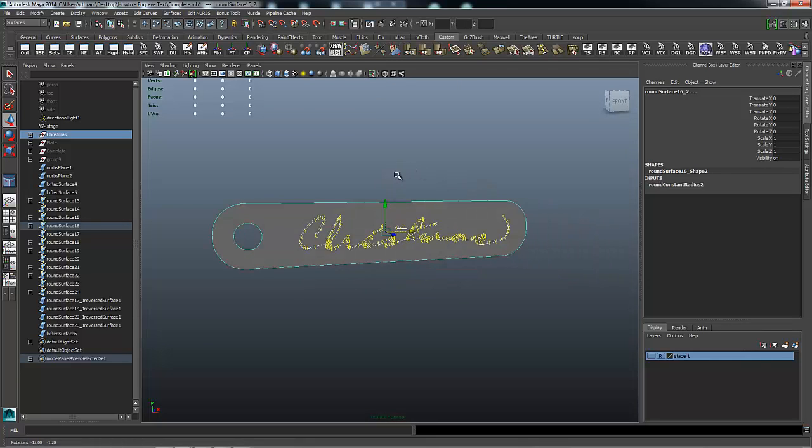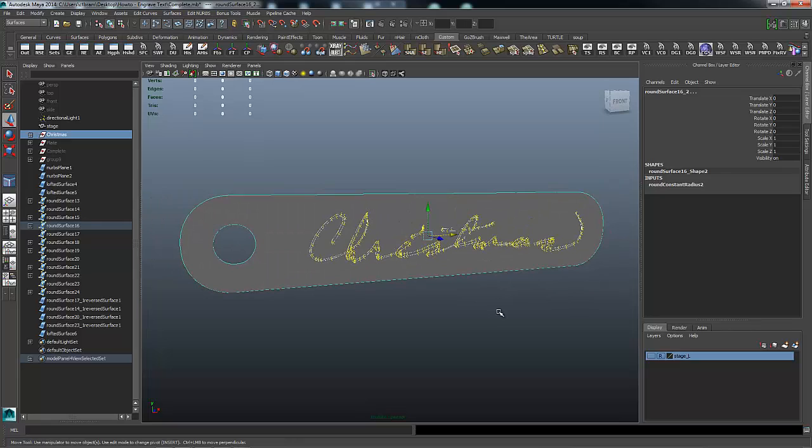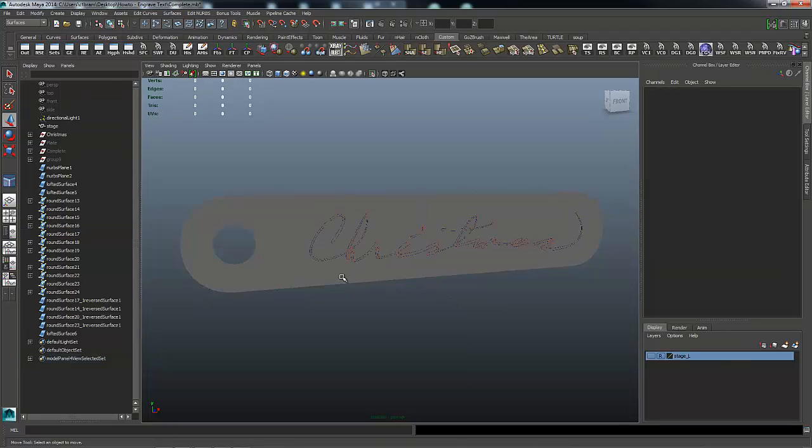And just like we did before, we're going to project these curves onto the surface, and then we're going to trim them out. Now the reason I didn't do that in one step is when you do the rounds, if I had engraved or trimmed out the hole for the letters and then tried to do the rounds, once again Maya acts very oddly, and all of a sudden you get areas of this text that will fill back in again. So to eliminate that, I'm breaking this up into steps, and this just comes from experience using Maya, knowing how the trim tool behaves properly, or misbehaves in this case.